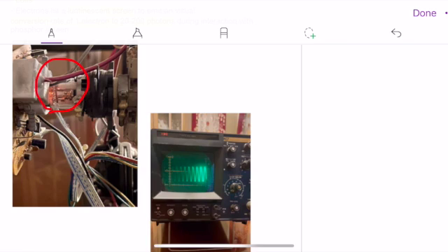Furthermore, in this video, we can see a green light. This green light is going up and down, making wavelengths. These wavelengths are approximately negative values to positive values, back to negative values. This wavelength is affecting the X value. So, based on the screen, we can determine that at least one of the coils is activated, that being the coil that deflects upon the X-axis. As this coil is activated, there's a manipulation to the stream of electrons being emitted through the electron gun, which proves our point of the cathode ray tube.